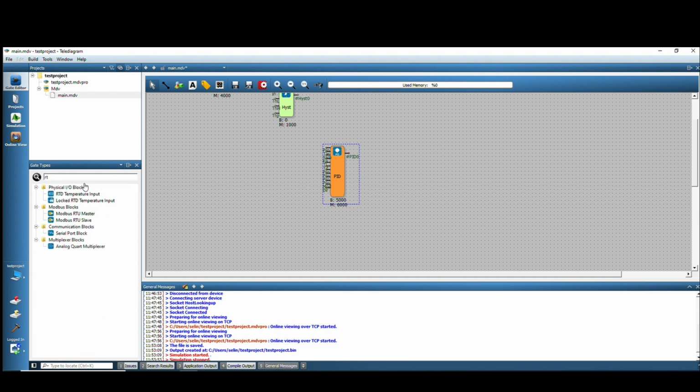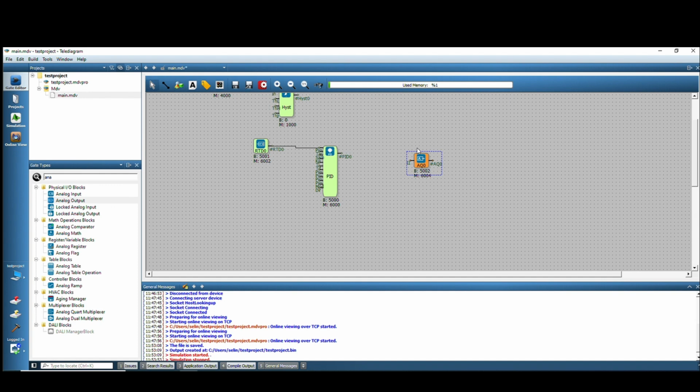For example, you connected an RTD temperature input to the Pro input. You write the desired temperature value for this RTD PT1000 sensor. What will be controlled next? A servo motor can be driven, or a different control can be implemented, or analog control can be performed by connecting an analog output and managing your FBD controls in this manner. According to this analog output, control can be done either with a 4 to 20 mA current output or a 0 to 10 V voltage output.